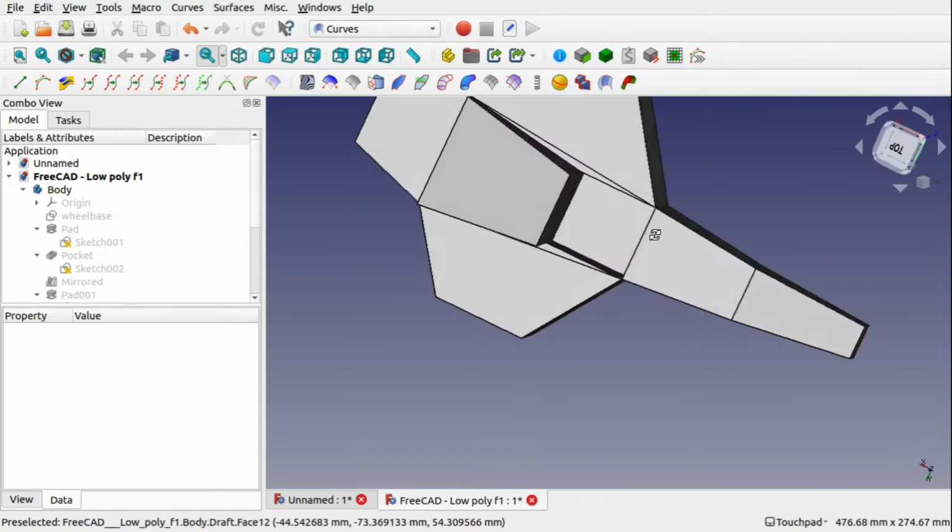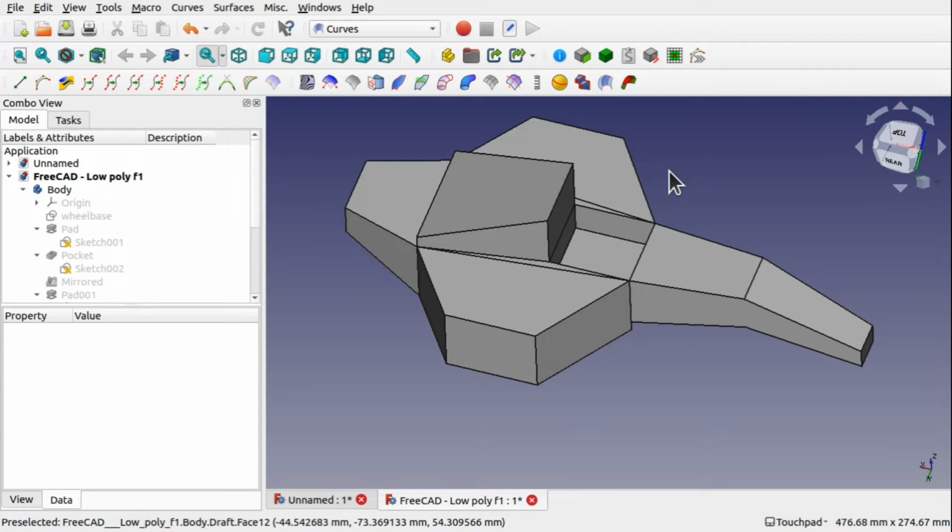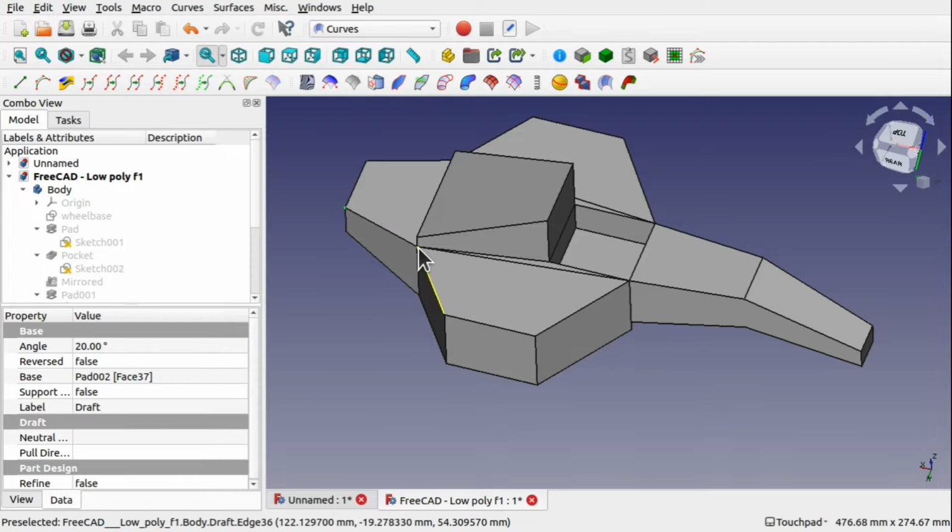At the moment I've got so far, so we can use the interpolation curve to actually pull out curves from this object to create a surface. If I select some of these vertices in here, you can increase the size of the points of the model to make this a lot easier. Then we can use the tool and create a curve through those, and then again we could do the same down here.